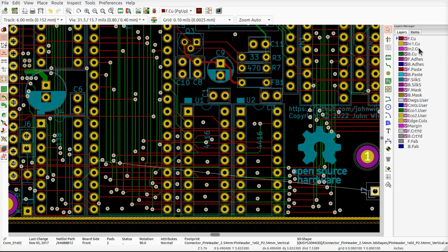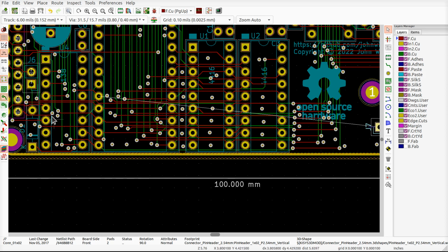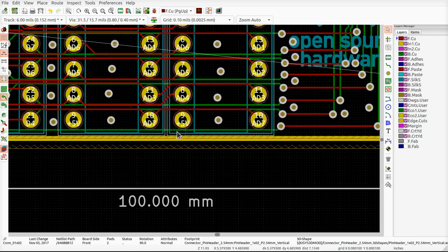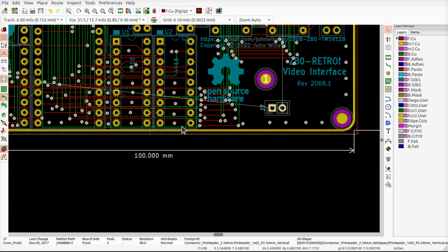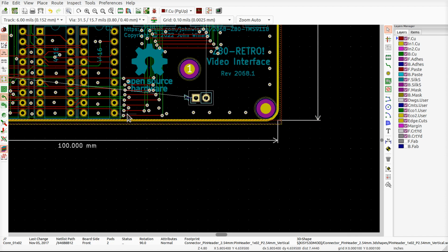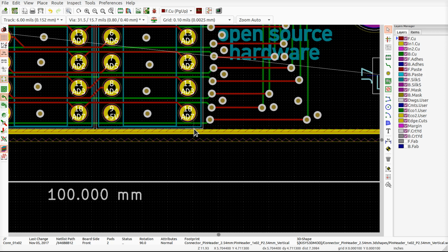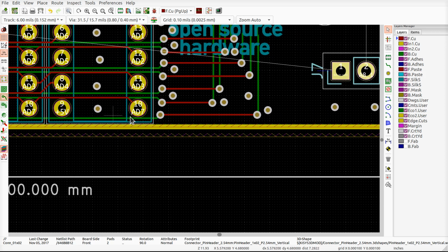Yes. Oh, we do have inside layers. This is a really gratuitous use of inside layers, but that's fine. That's fantastic. That means there's a ground plane and a power plane in here between the front and the back, so this back track will not go too nuts radiating through the board. Yes, it's all the way out at the edge, and yes, it could be worse. It could have been done a little bit better than that. It'll be fine. We're going to run it around the outside edge.